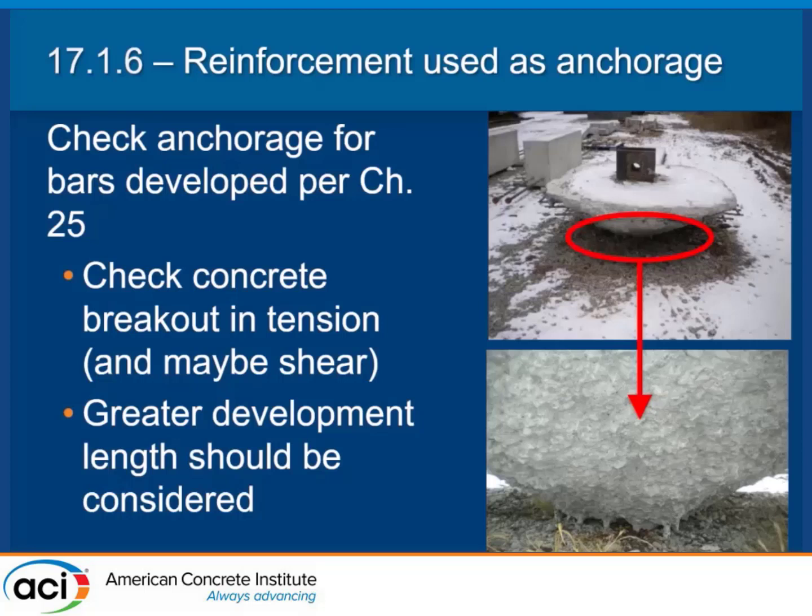But no, they had these reinforcing steels. They were developed. They went down, and the force got large enough that it actually pulled out of the concrete, and it did so at a 35-degree angle. Isn't that amazing? So this is what happens. Doesn't matter how big, how small, that is the failure you're getting in tension. And here you can see the reinforcing steel sticking out and how many they had in there.